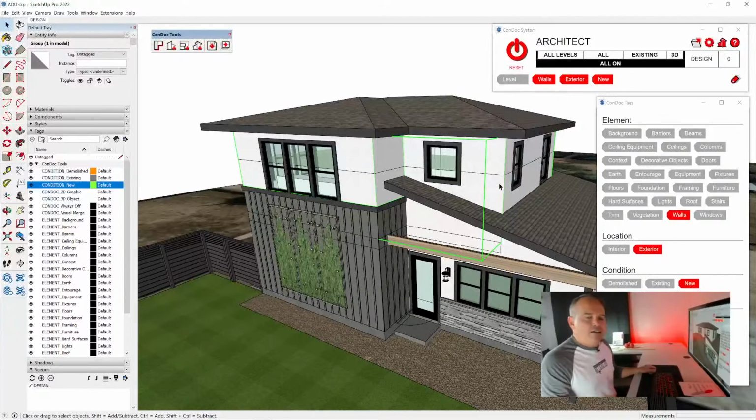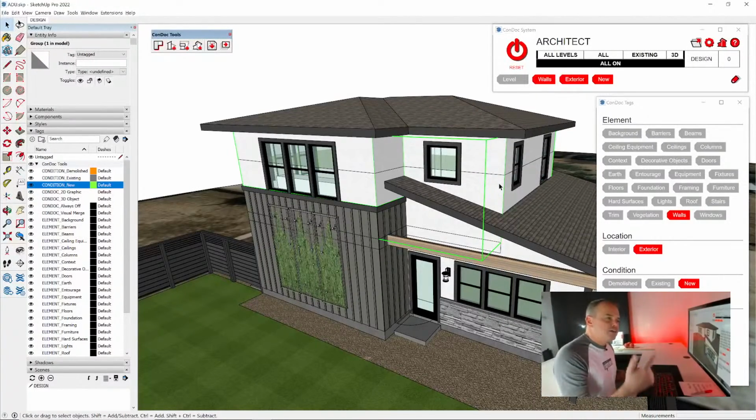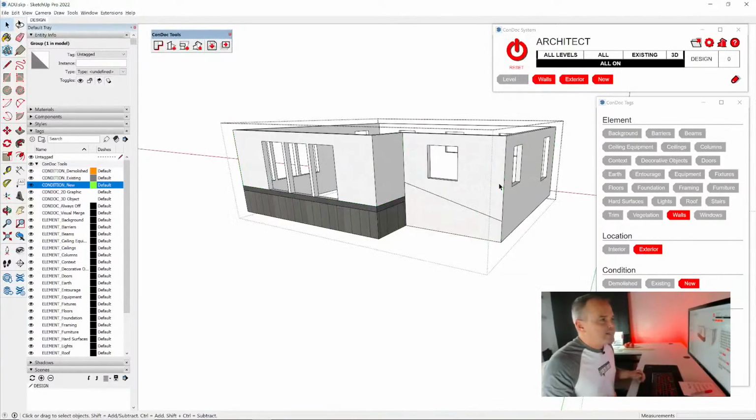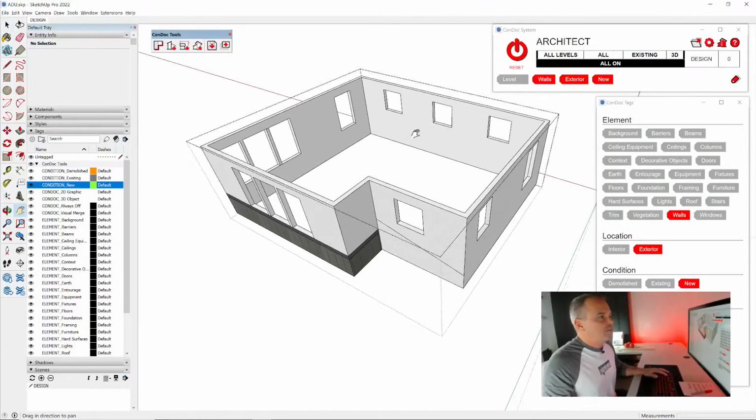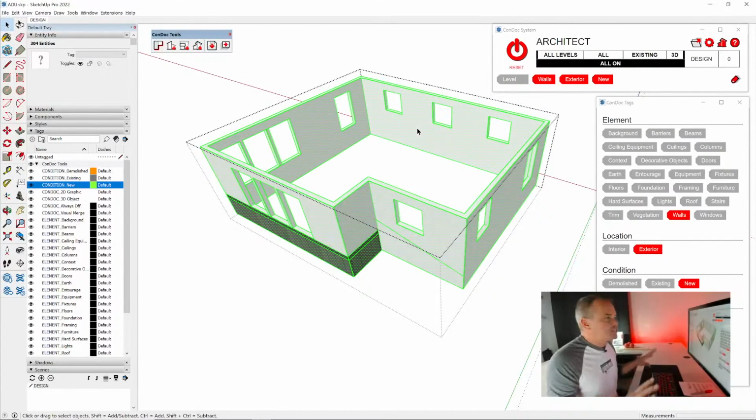We've essentially assigned multiple SketchUp tags to one object, and we maintain the ability to double click in one time and access all the edges and surfaces, so we don't have this nested shell game of groups within groups within groups, tags and tags and tags.